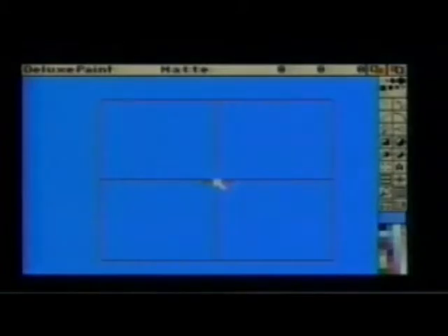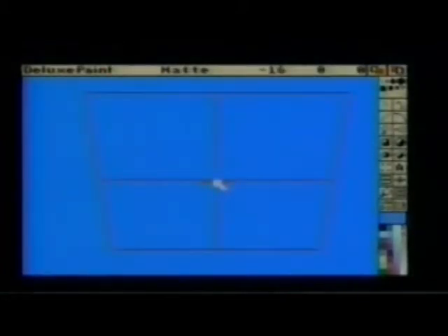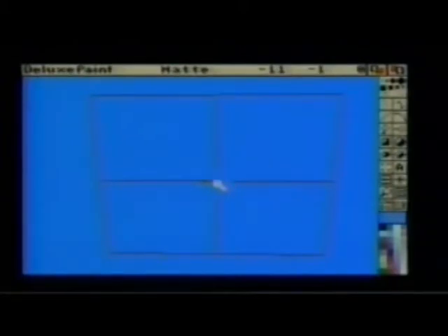The perspective mode is another versatile tool. After a brush is cut out, swap to a spare screen with the J key or menu option. Pressing the Enter key on the keypad enters perspective mode. A rectangle that represents the size of the brush can be rotated around its 3 axes by playing with the number keys.